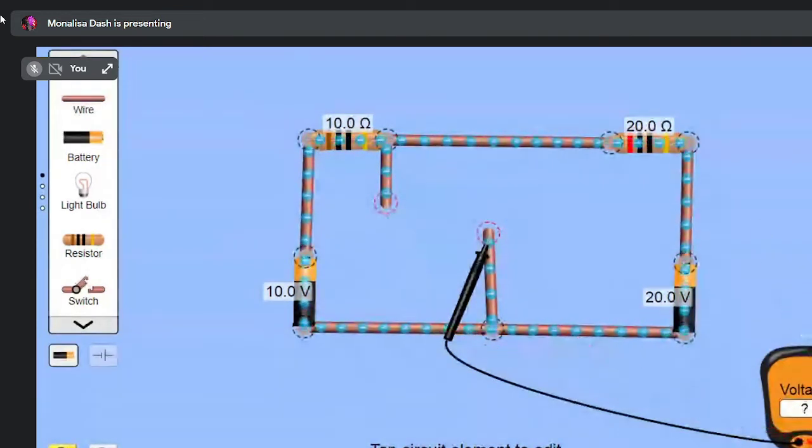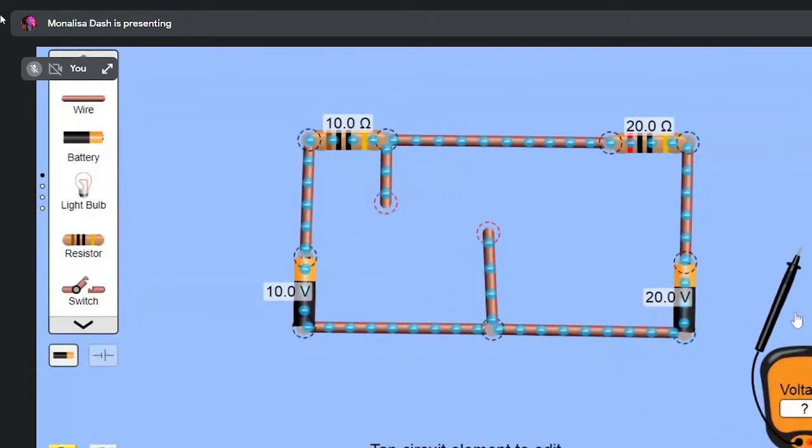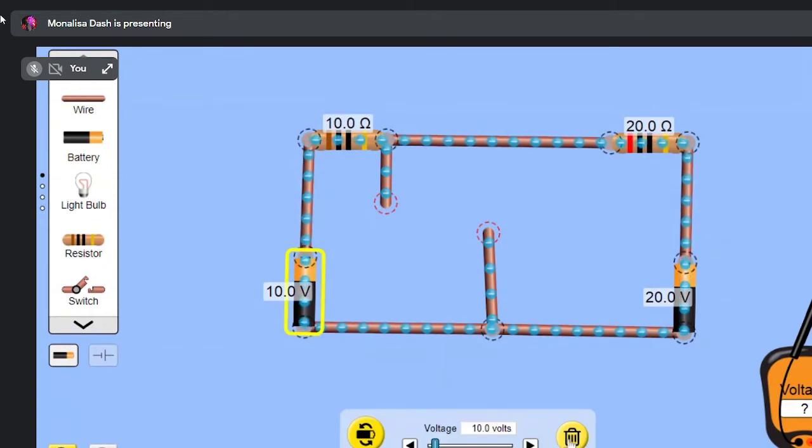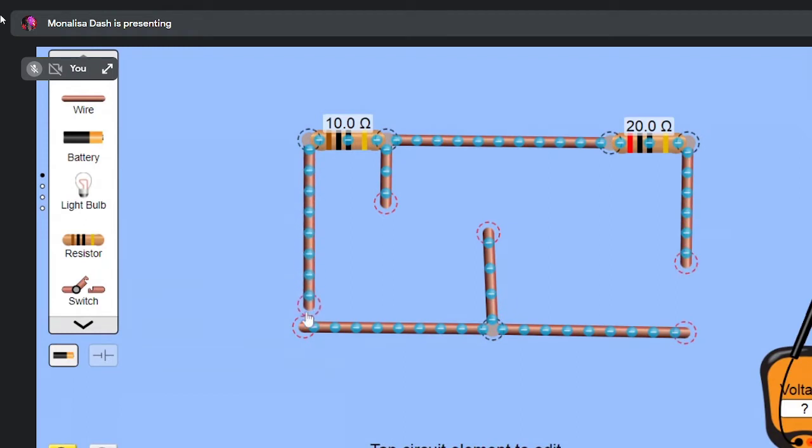So now we are going to the next circuit. We have to determine the RTH. Theoretically you have to put 10 and 20 in parallel. But practically, you remove this part also, short circuiting it. And for resistance measurement, you need a battery and an ammeter.